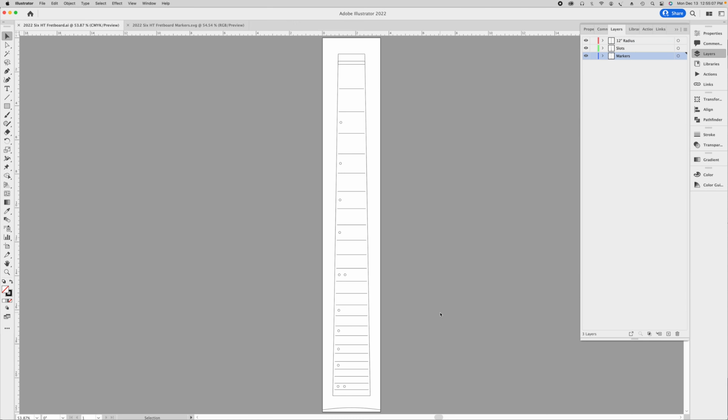The first operation that I have to perform in order to carve this fretboard is a simple 2D carving where I will be cutting out the holes for the fret marker dots as well as the slot for the nut. And since this is a simple 2D carving operation, it's going to be done using an SVG file, as I mentioned before. And I save that out separate from this file. And this is what the SVG file looks like.